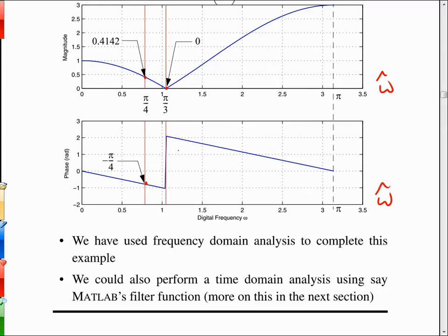One form of jamming is called tone jamming. It's not at an audible tone, it's at a microwave or RF frequency, but it's just simply to broadcast a pure tone and just throw it up there in the face of the enemy's receiver so that it kind of gets saturated with that pure tone. And the idea is to put that tone in the bandwidth of the receiver front end so it kind of makes it go crazy. It can't handle all that tone jamming.